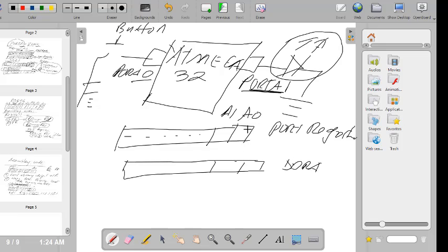DDRn. So here is the point. Port register has to do with the status, right? So I need to think, okay, what should be the status of port A0? Now I want to mention here, guys, that I'll just give you the status. So the status of an input port, mainly we write a 1. I will show you the reason why in the next lesson. So I'll say that port A0, I'll give it a high status, all right?